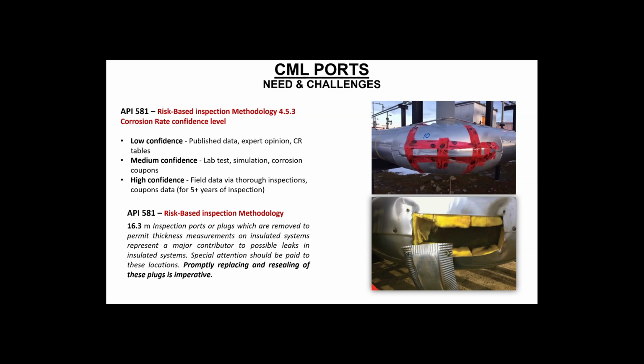But if you look at the scenarios on the right side, we can see some duct tape or some warning tape being placed on these inspection points. And also we can see crimped metal panel on these inspection points. So these are the points where the moisture is going to infiltrate and cause some accelerated corrosion. Two bad things will happen if these inspection ports are not managed and sealed properly. First, it's going to allow the moisture to infiltrate, causing more corrosion, such as CUI. Plus, it's going to corrode the system more.